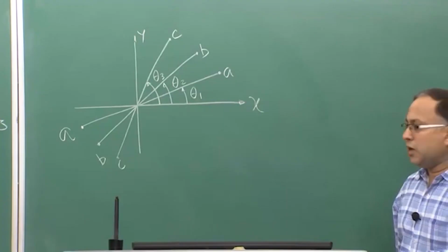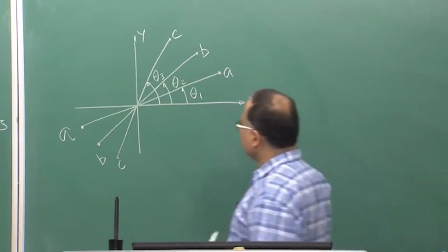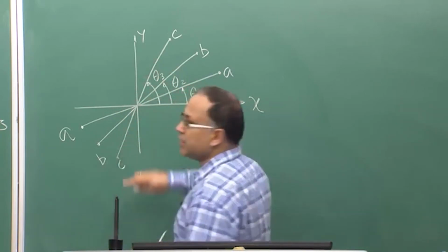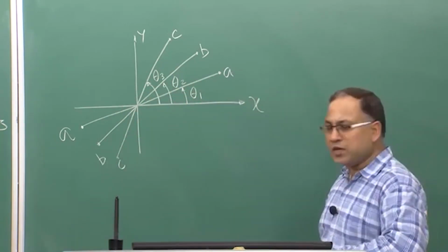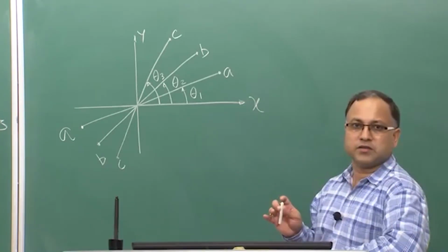And we are fixing the strain gauge along AA direction, BB direction and CC direction. So, three strain gauges we are putting and we are observing three normal strain components.